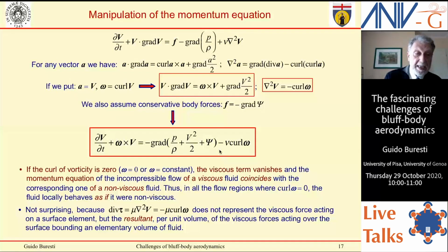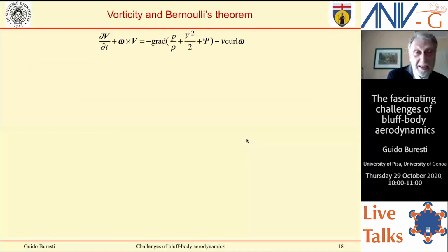And this is true because this term does not represent the viscous force acting on a surface of the fluid, but the resultant per unit volume of the viscous forces acting over an elementary volume of fluid. These equations refer to the motion of elementary volumes of fluids.